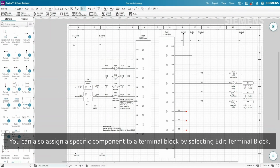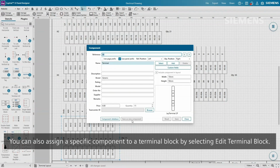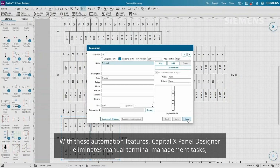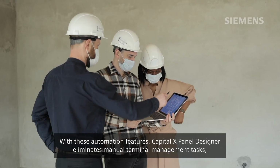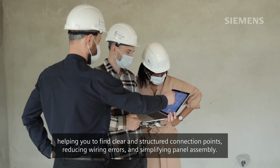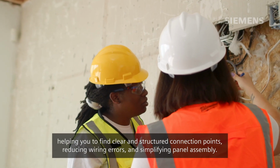If needed, you can also assign a specific component to a terminal block by selecting Edit Terminal Block. You may select or add a custom terminal from the component database or even adjust its layout. With these automation features, X Panel Designer eliminates manual terminal management tasks, helping you define clear and structured connection points, reducing wiring errors, and simplifying panel assembly.